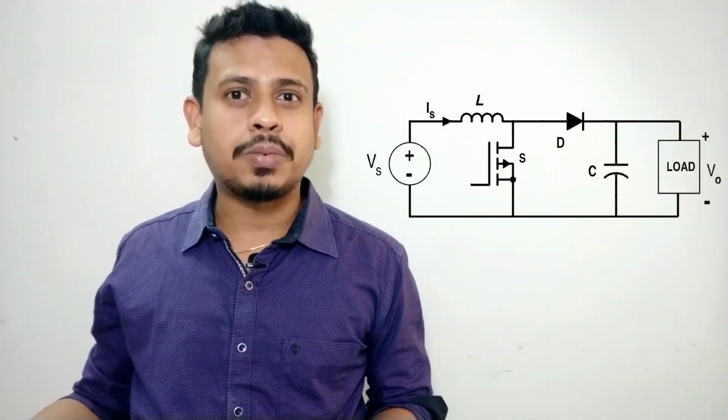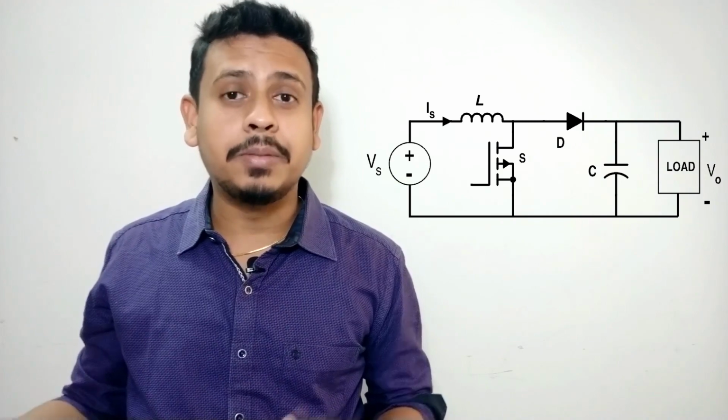If we have to generate a higher voltage power supply from a lower voltage power supply, there are a few topologies of power converters that would be capable of doing this operation. A good example will be a boost converter. The idea of using an amplifier circuit in order to generate a higher output voltage is not a very advisable one.